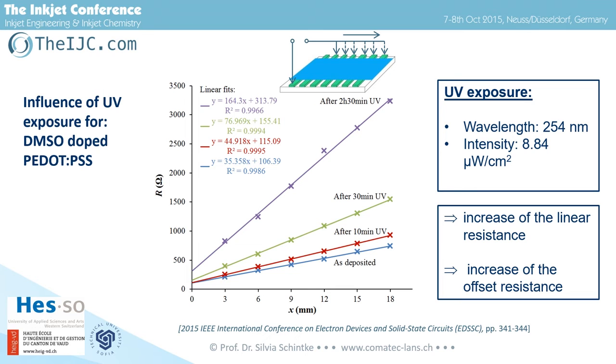So this means that there is a decrease in conductivity and there is some degradation when we expose the PEDOT:PSS to UV. The values which you see here are already the better case. In fact, we doped our PEDOT:PSS with dimethyl sulfoxide, and this increases the conductivity dramatically by a factor of 1,000. One finds this in literature, the conductivity of PEDOT:PSS. So this is already a good case.